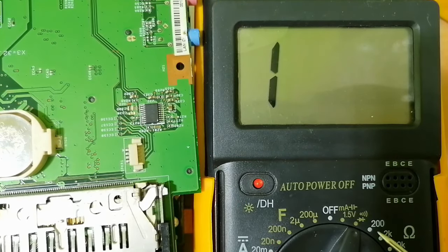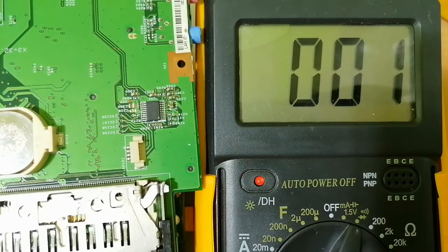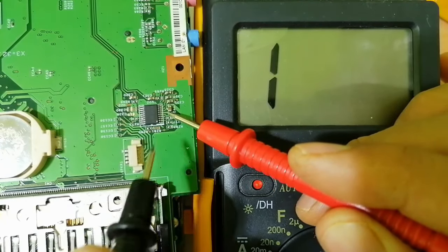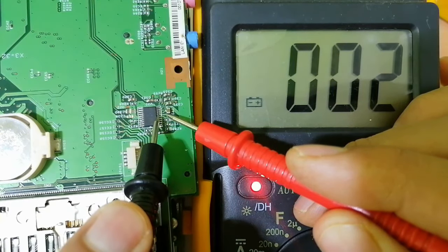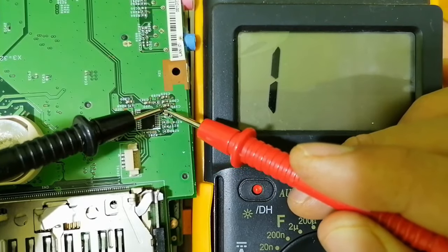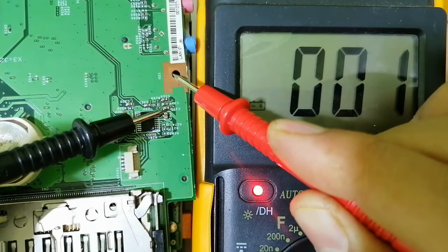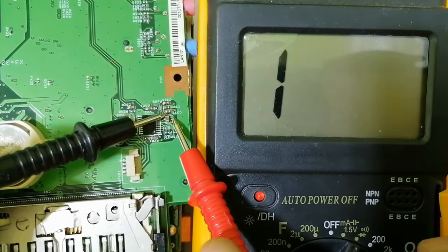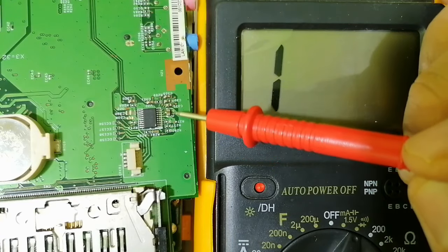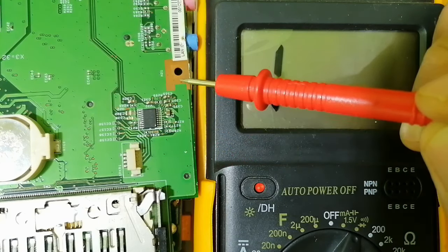So let's put the multimeter to the continuity option. As you can see, let's check. The continuity option is set correctly. So if I put one probe here and the other probe on this terminal, do you see? This ceramic capacitor is connected to the IC in this terminal. But the other terminal of this capacitor is connected to the ground. Do you see? Why? Because we have this path over here connected to ground. This is ground, basically. So all capacitors around the IC, you will find connected to the IC on one side and to the ground on the other side.